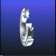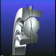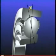The contact angle is 0 for bearings that do not have any thrust loading, such as this ball bearing. This angular contact ball bearing has a contact angle of 30 degrees. It is measured from the center line of the balls to the center of the curve. It is important to know the exact contact angle because